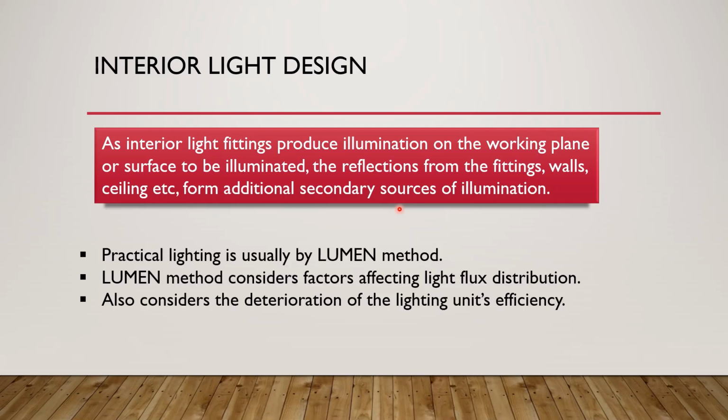So practical lighting schemes are usually designed by the lumen method. Instead of using those two laws, we are looking at the lumen method. The lumen method considers all the factors that affect light flux distribution, and it also considers the deterioration of the lighting unit's efficiency. So you consider all the things that will obstruct the distribution of the light flux in the interior design, and you also take into account the efficiency of the lighting fittings and the light source itself, because it can deteriorate over time.